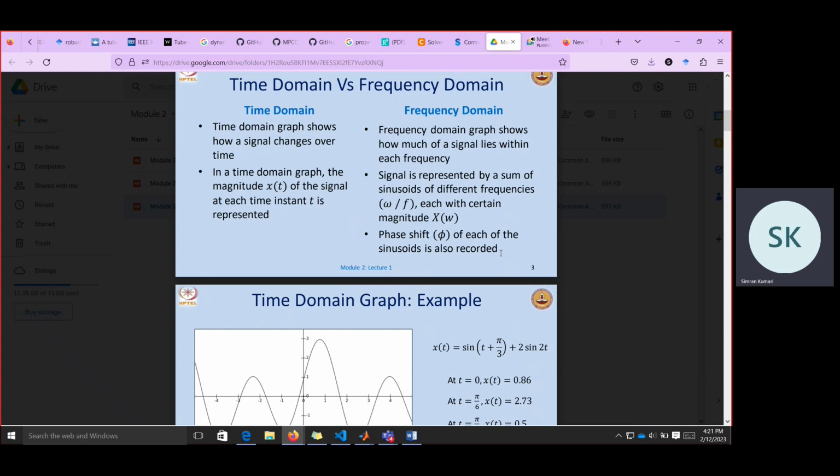Yeah, this is for LTI systems. If you go to a non-linear system and pass a sinusoidal signal, then the output will have different frequencies. But for this one, we have the same frequency. It's just that amplitude and phase will shift, and that we use in frequency domain analysis. Also, when we are finding the transfer function, what are we trying to calculate? We are trying to see the response of the system to different frequencies of signal.